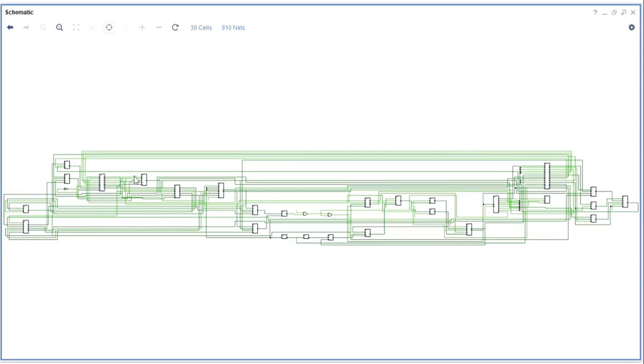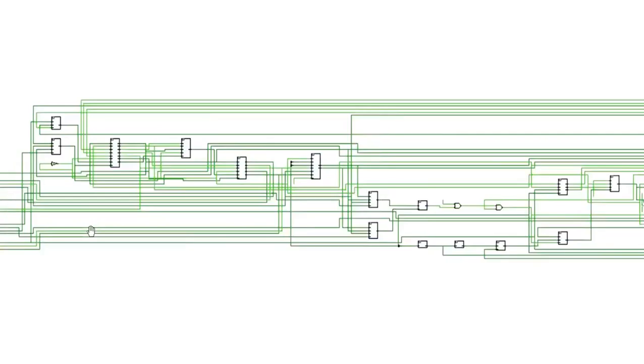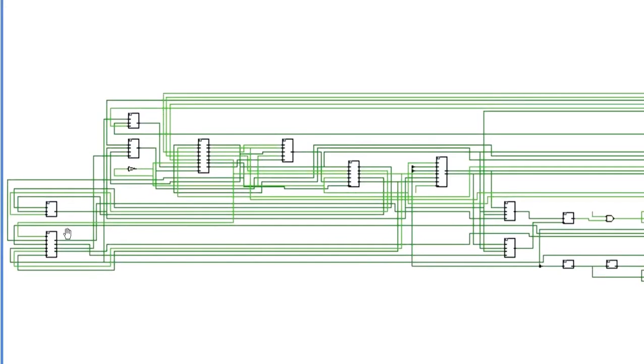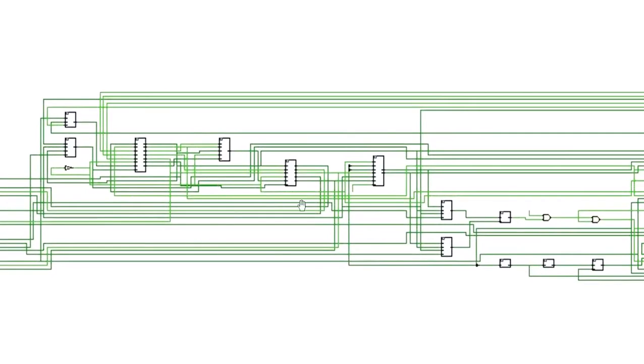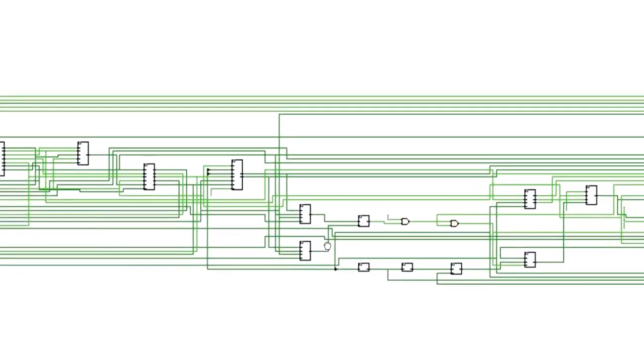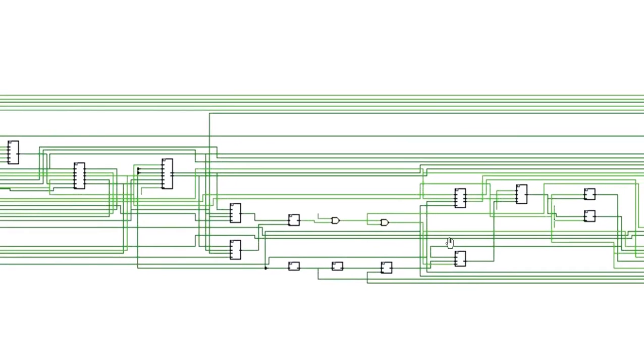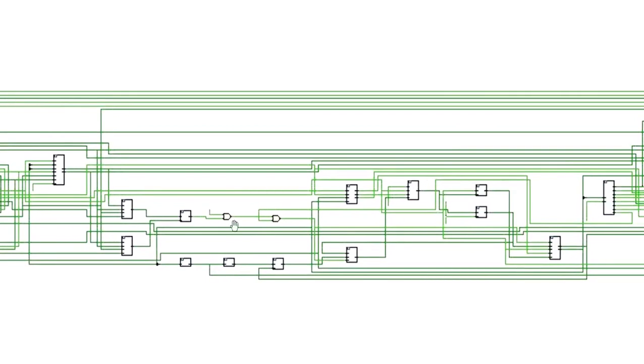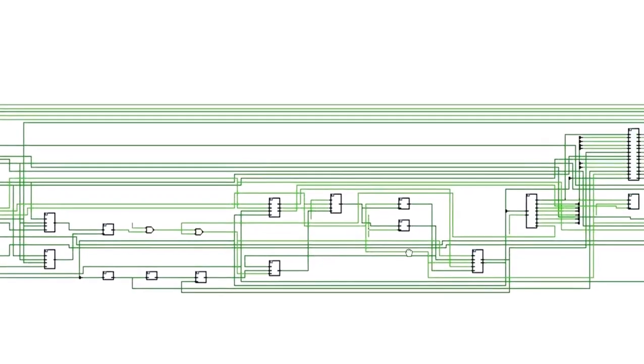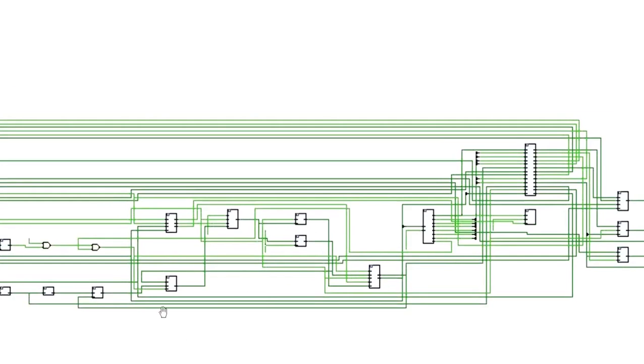And this is the schematic diagram we obtained by executing the code. It represents multiple blocks. Each block represents a stage, like instruction fetch, instruction decode, then execute stage, then memory stage, and write back stage. It presents adders, multiplexers and arithmetic logic units.